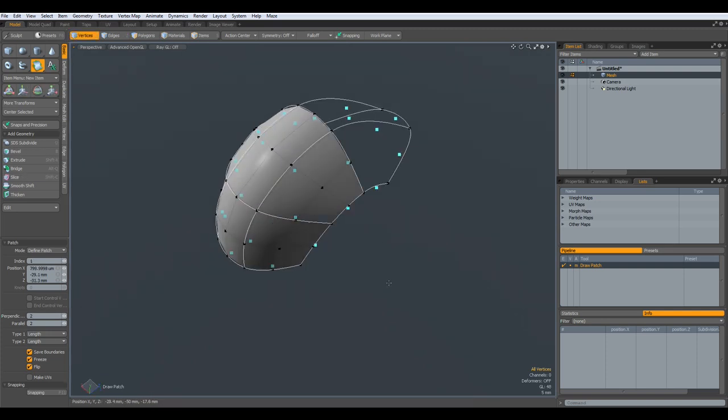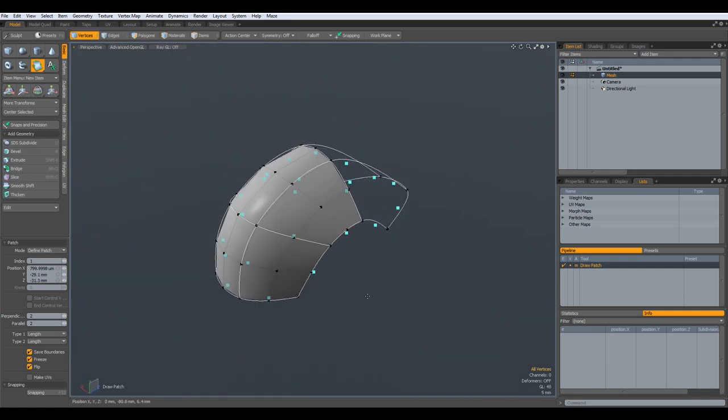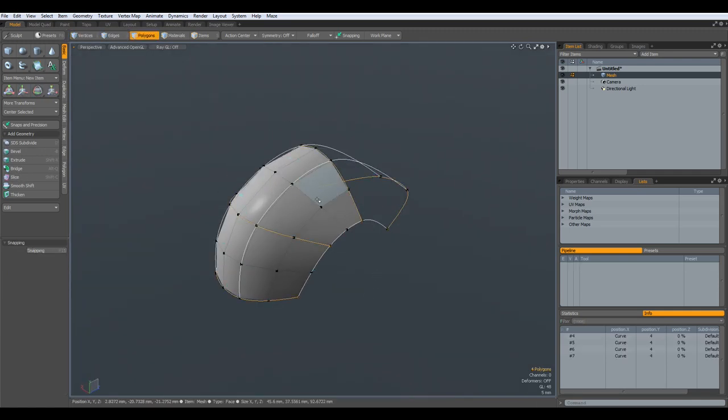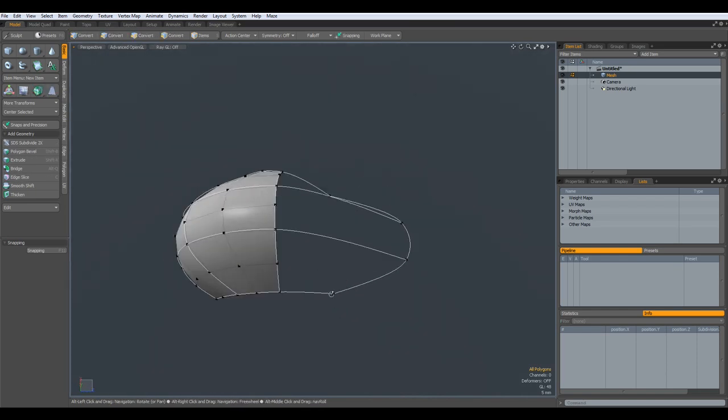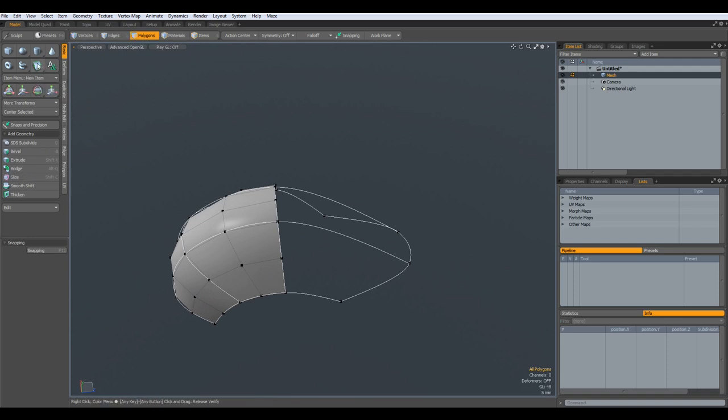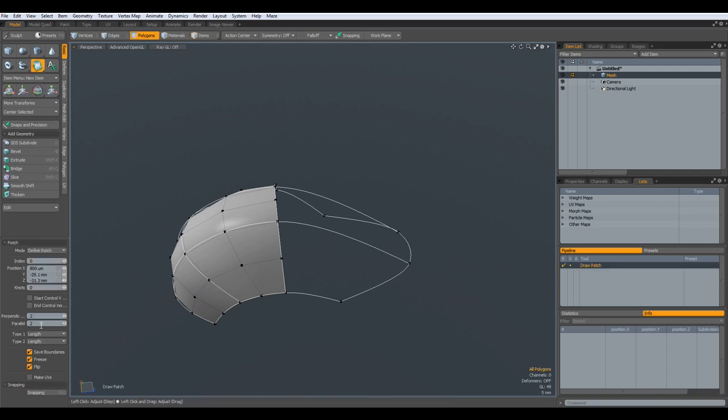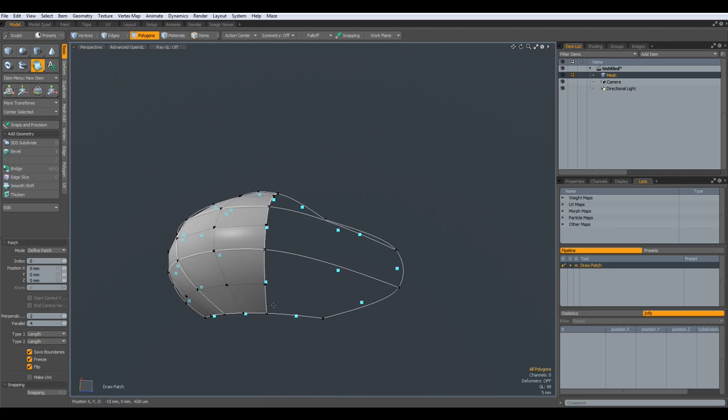Okay, now drop the tool. Then I select these new polygons and hit the J key to lock this geometry. And now we can change the tool settings from 2 by 2 to 2 by 4. And remember, perpendicular is the one which we select first. So this one, for example.